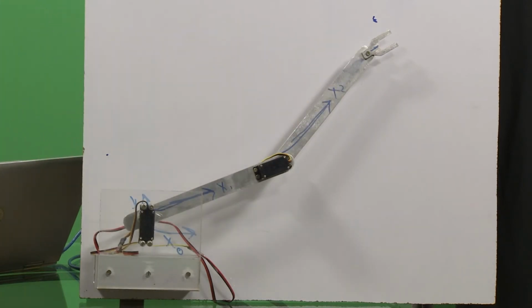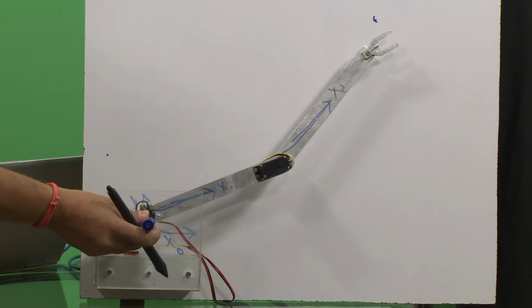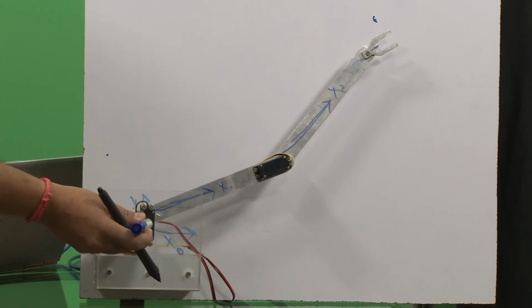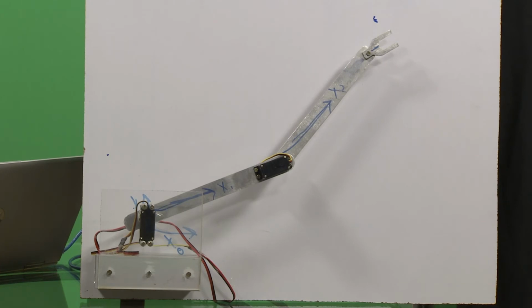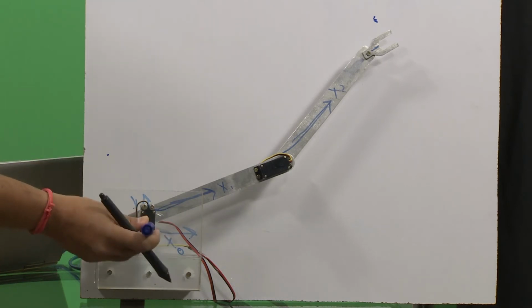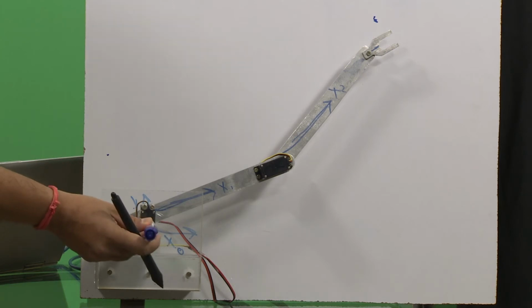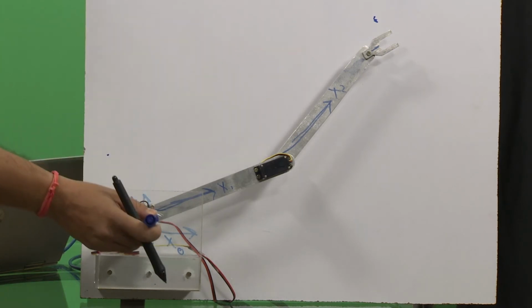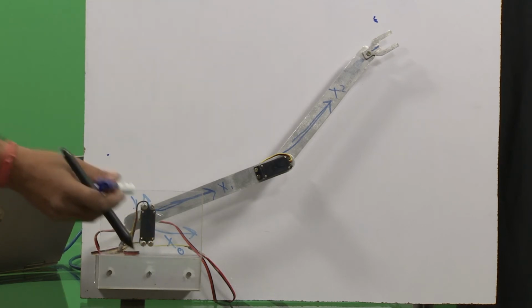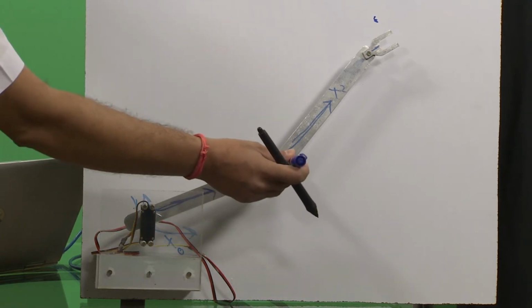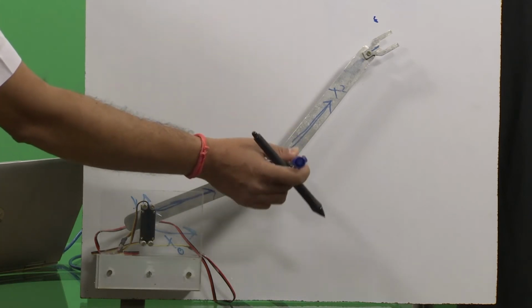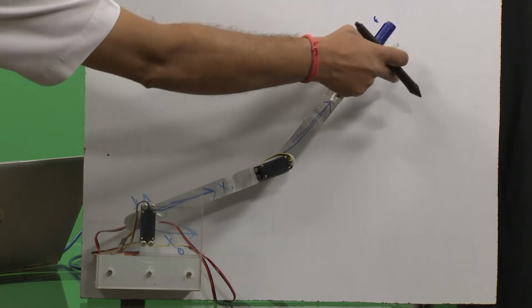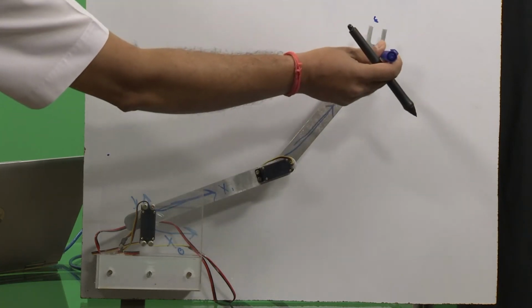Now, DH parameters essentially tell us how we assign our axes such that it becomes very, very simple and you need to do the least number of computations. What the DH parameter says is that the axis of rotation, or the axis of translation, is the z axis. In this case z0 is here, the reference which does not move, z1 is fixed onto the first axis or the first link, which is this one. Both of them, z0 and z1, are the same axis. Next, z2 is here. This is also a revolute joint, and there is a small link there which can rotate about that, if you can see. So, this one is my z3 axis now.